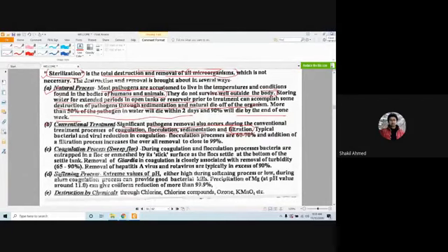And they're saying that typical bacterial and viral reduction in the coagulation flocculation process is 60 to 70%. Okay, and the addition of a filtration process can increase the removal close to 99%. So conventional treatment, that's one thing.